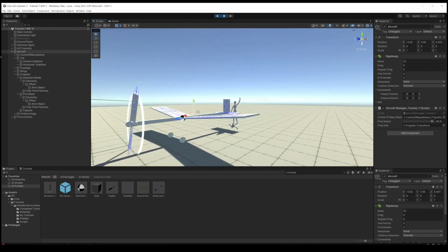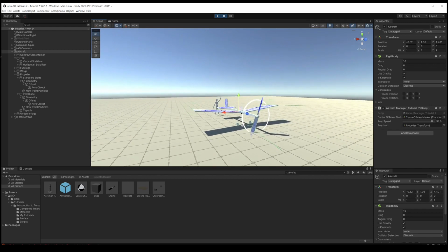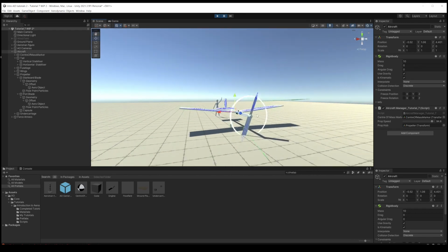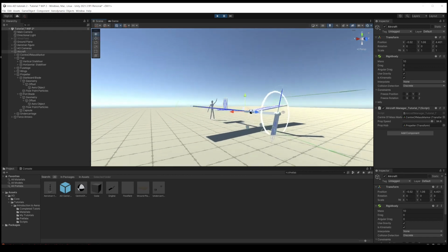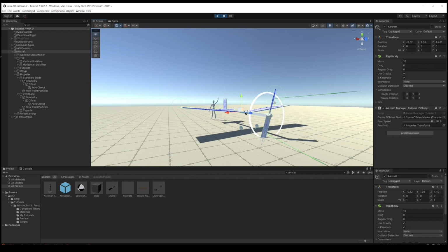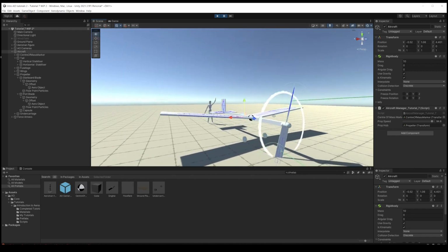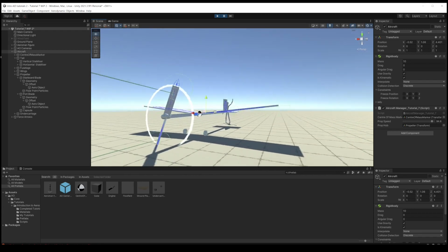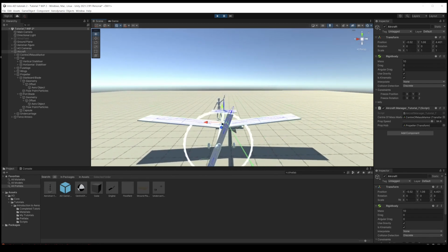And if I pause it, you can see those green arrows are basically what we saw as the lift arrows on the wing. The aircraft isn't moving, but the propeller is spinning round, and those lift arrows coming out the center of where we've got these objects, 0.75 along the blade, is generating lift, and that turns into thrust on the aircraft. Great.